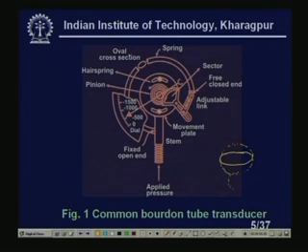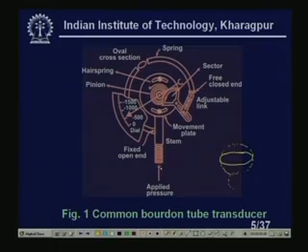The scale is written either in PSI, pounds per square inch, or in kilopascal. Again I am telling you, see the fixed open end, the liquid side, and there is a thread so that it can be put on the vessel in which I am interested to measure the pressure. It is covered, you cannot see anything from outside; the dial will be on this side.